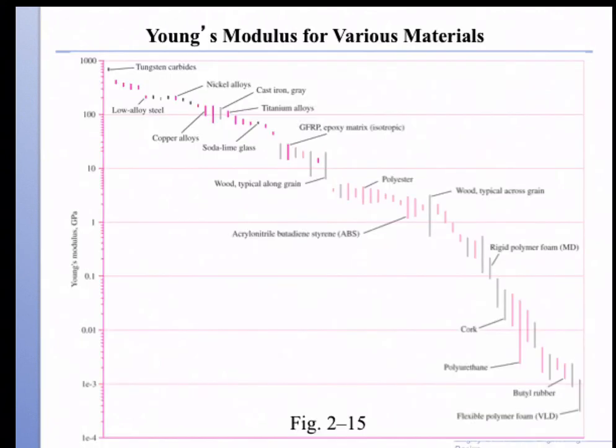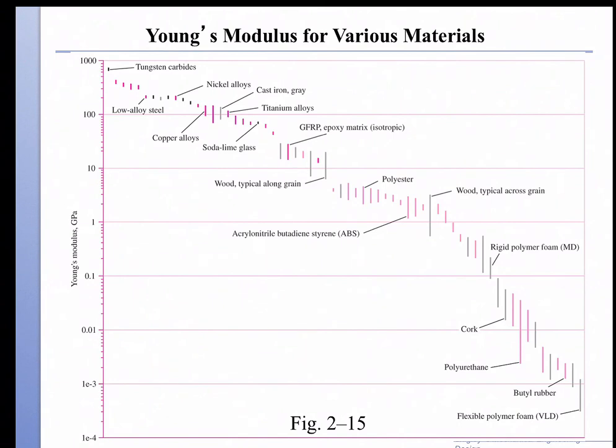And now, if we consider these families and we want to use them in a particular design, the design will have certain specifications in terms of the Young's modulus, for example, that is required. Or the weight, or a combination of the weight and the stiffness that's represented by Young's modulus.